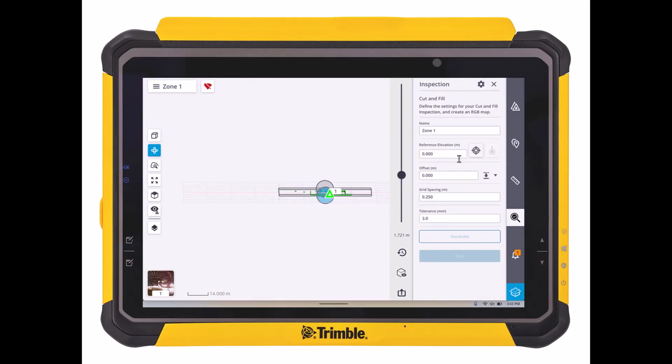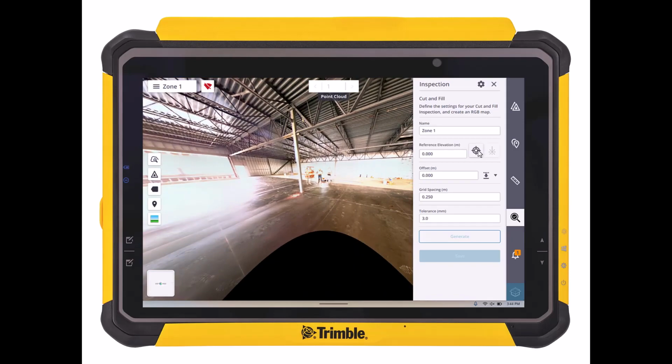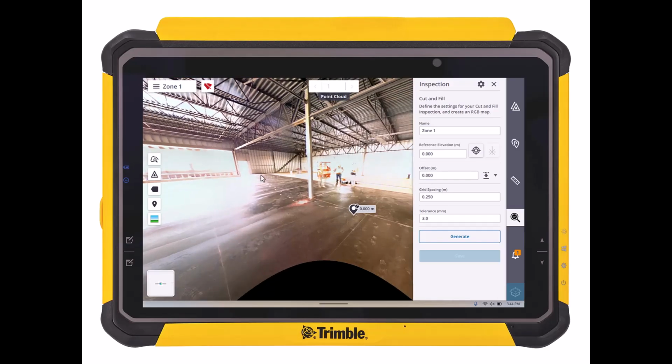Now the next thing that you'll want to do is select a reference elevation. Now I usually like to go into the station view because I can get a good clear view. Now I didn't do this scan, so I don't know the best place, so I'm just going to click right here. Now, if the laser scanner was still turned on and connected, we could use the laser pointer to point at a reference point and then take a precision shot. Now, in addition, if you had a benchmark, maybe over here against the wall or something, you could take your shot there and then select an offset either above or below that reference.